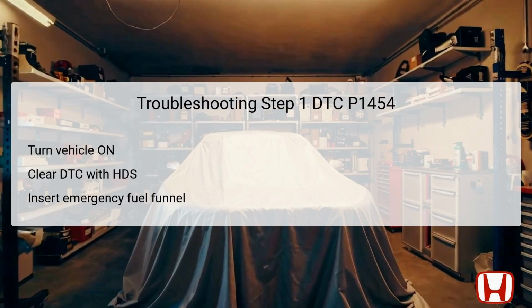In the first troubleshooting step for DTC P1454, begin by turning the vehicle to the on mode without starting the engine. This allows access to the vehicle's onboard diagnostic system. Next, using the Honda Diagnostic System, HDS, clear any existing DTCs to reset the system for further analysis.